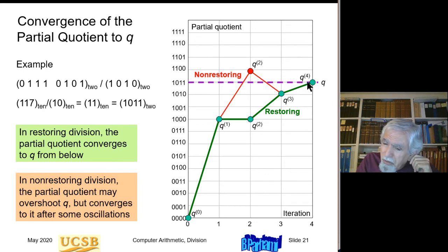Whereas when you use the non-restoring algorithm, here's what happened. First quotient digit is 1. Second quotient digit, we assume to be 1. We do the subtraction. But because the result went negative, we know that the quotient digit is 0. Okay, so it went negative, so we add to turn the remainder into a positive remainder, and then continue. So this detour, basically, the incorrect value is corrected in the next step.